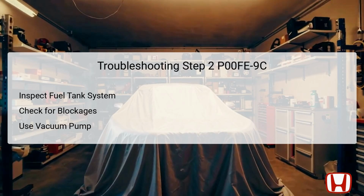Under normal conditions, pressure should not be held. If it is held, that indicates a blockage within the fuel tank system that needs to be resolved before further testing.